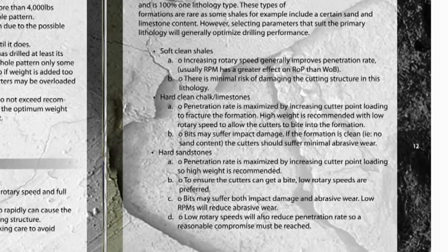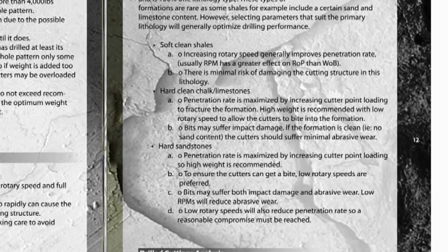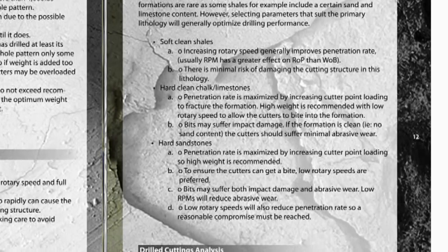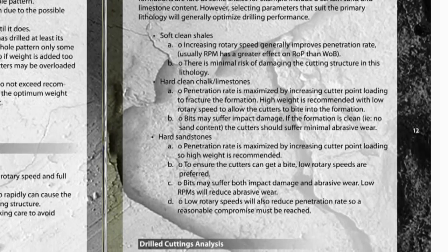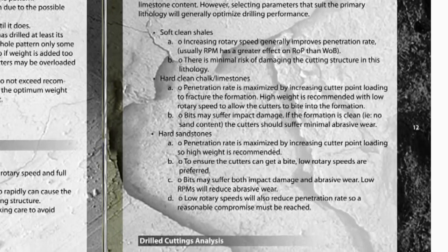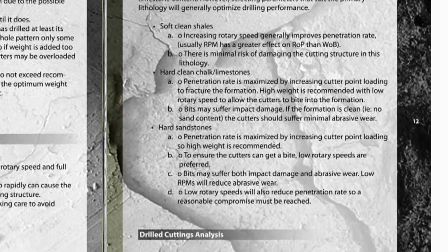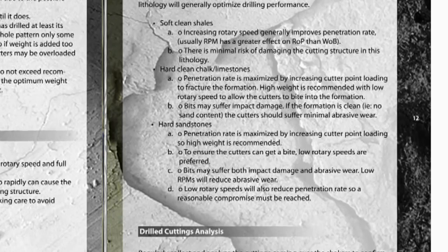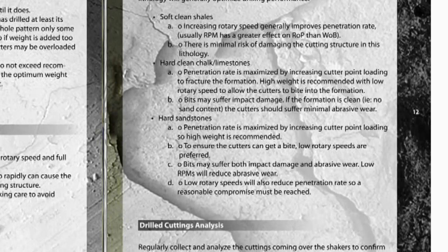Hard, clean chalk or limestones. Penetration rate is maximized by increasing cutter point loading to fracture the formation. High weight is recommended with low rotary speed to allow the cutters to bite into the formation. Bits may suffer impact damage. If the formation is clean, i.e. no sand content, the cutters should suffer minimal abrasive wear.